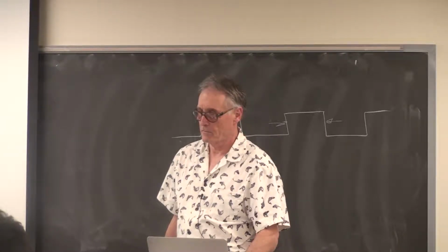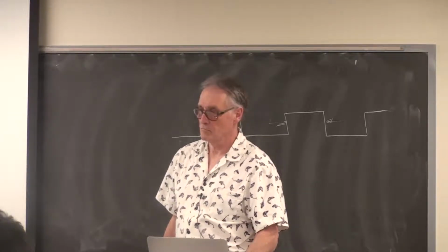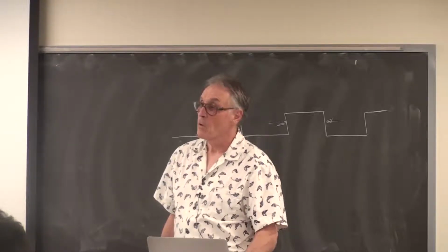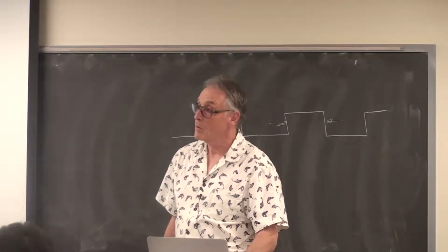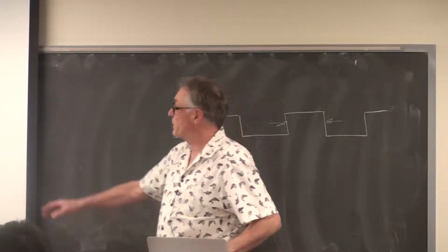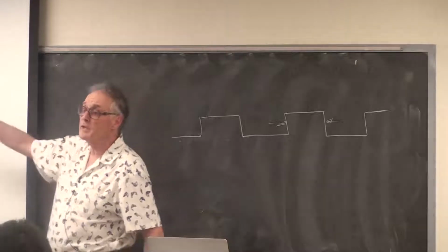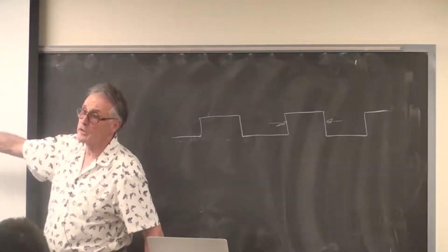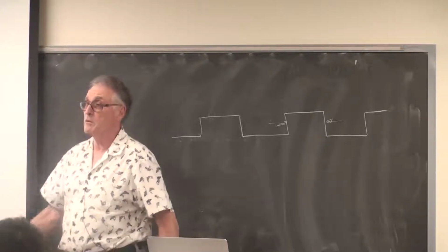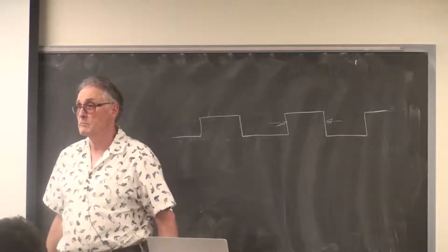Okay, so the open output compare function takes in configuration and then two values, and you're passing a PWM on time for both of them. What I would assume that does is one of them sets the on time, one of them sets the off time. Yes, which you are immediately going to modify with the PWM set time call in the interrupt service routine. Right, but don't you need the on time and the off time to sum to the period?